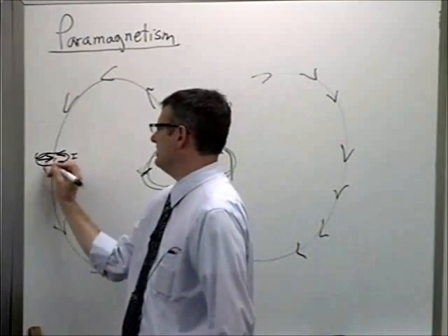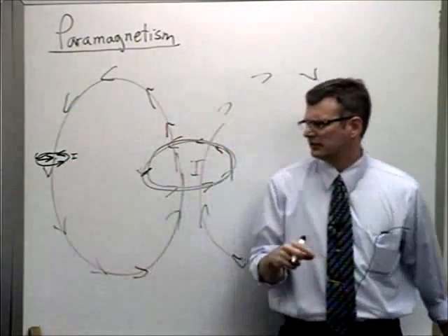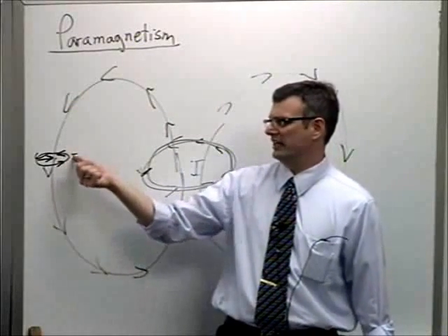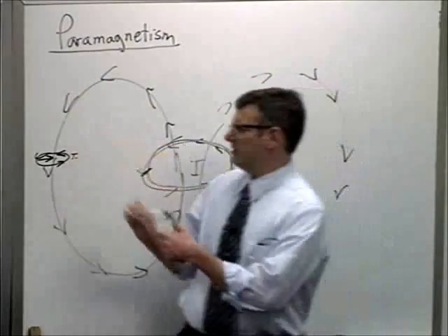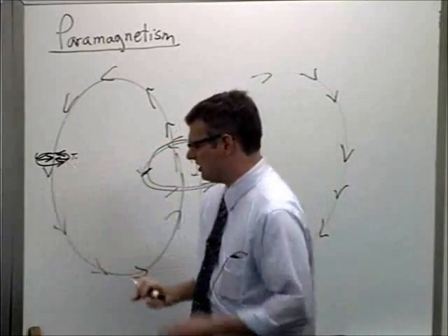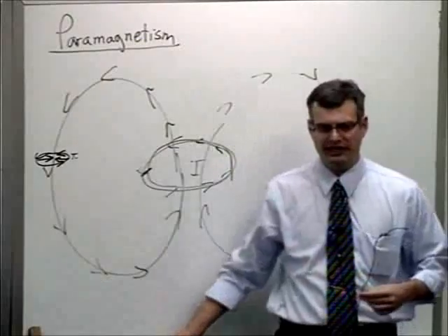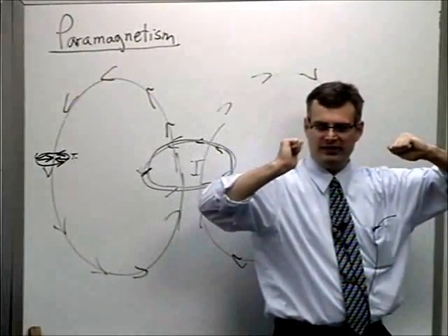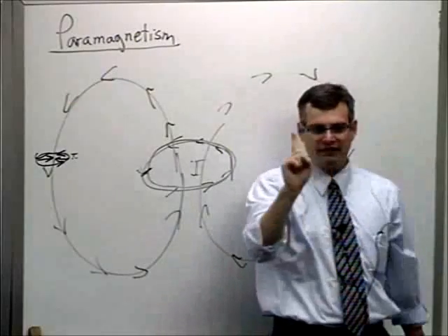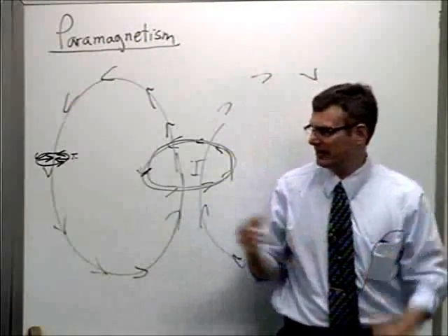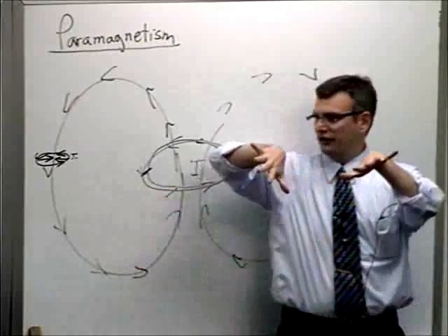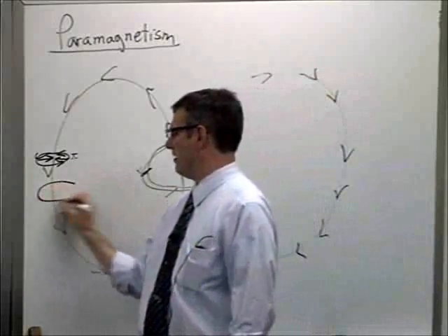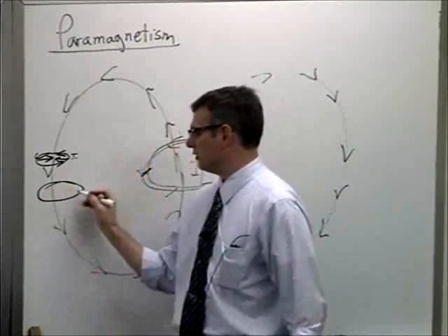So this force is going to be inward. And on this side of the loop, where the current's going into the board, that force is going to be inward as well. So what does that loop actually want to do at that point? If I'm pushing it on both sides, what it's really going to want to do is flip. And that's a very standard result in classical electromagnetics. Current loops will want to flip their polarities with respect to one another. This will actually want to turn, through mechanical forces, into a loop that does this.